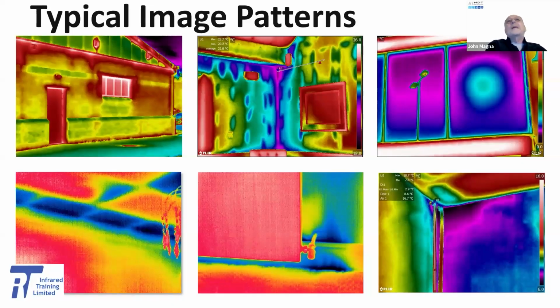For successful building energy performance surveys, we need certain environmental conditions. Depending on the nature of the survey, ideally this requirement is for as close to possible steady state heat transfer, and with a stable temperature difference, delta T, of a minimum of 10 degrees Celsius. No solar gain or moisture on the structure and little wind. And for air leakage identification, we need a developed pressure differential across the structure. And once thermally focused, we can determine anomalies qualitatively by comparison and by recognizing typical patterns.